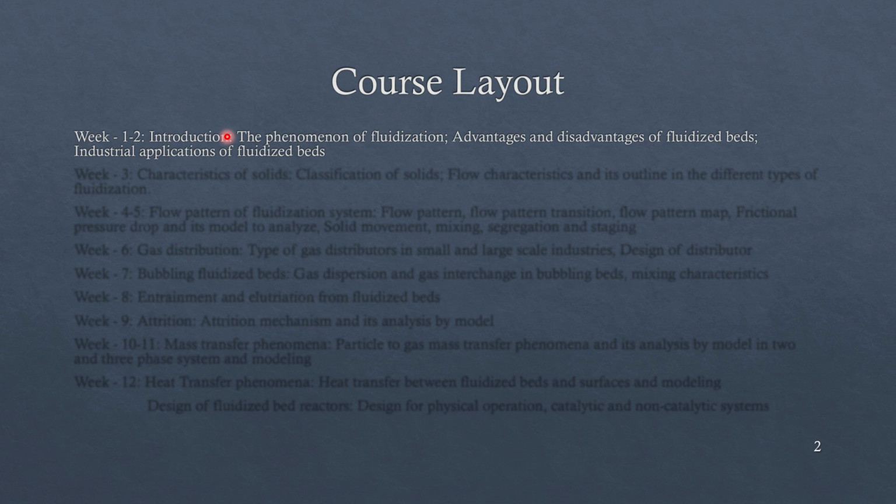So what are the advantages of fluidized bed? Because the particles behave like a fluid medium, we can avoid hotspot formation when we are using fluidized beds. Because in packed beds, a major disadvantage is that there are chances for hotspot formation, which is completely avoided when we are using fluidized beds.